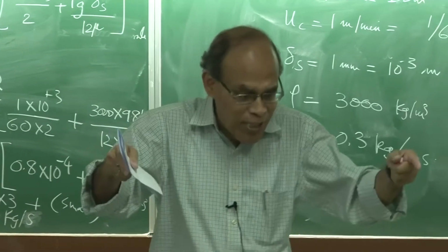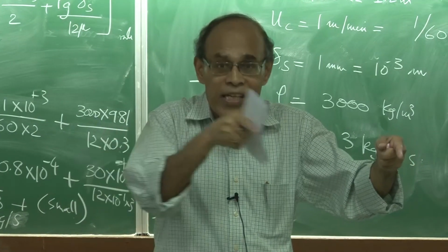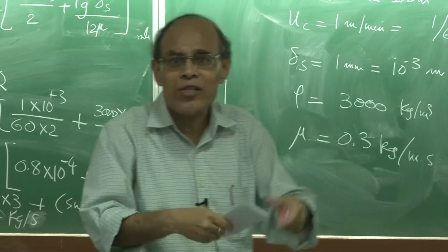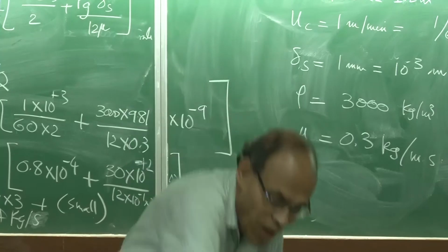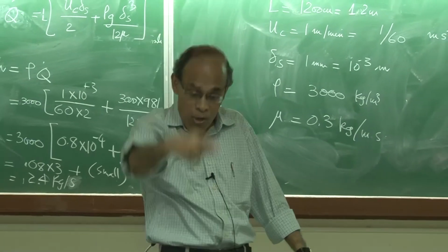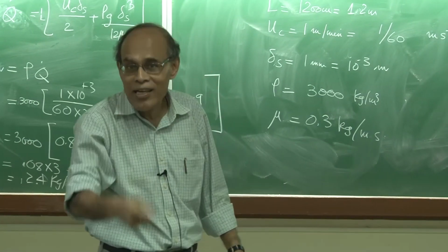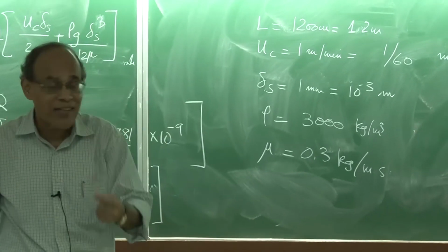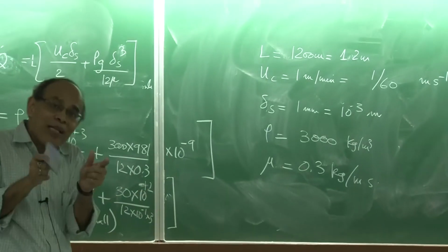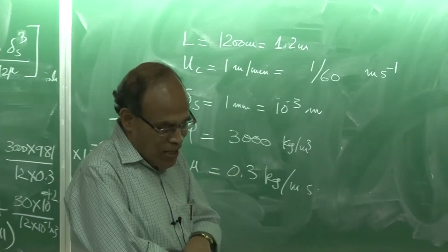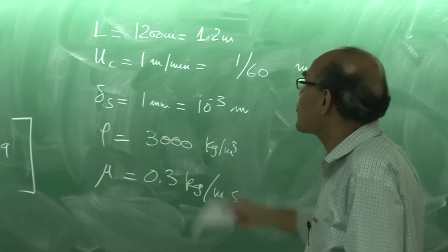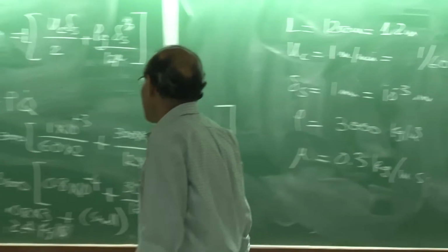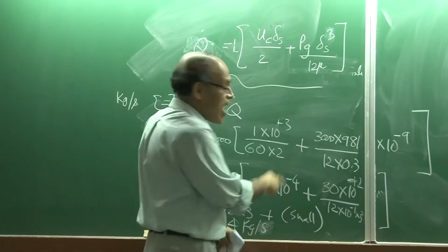So, the powder itself is in a range of states. It is somewhere solid, somewhere crystalline, somewhere liquid. It is a horrendously complex process, and sometimes the mold goes down and then, with the reciprocating motion, it comes up. So within the powder itself, there is a changing flow pattern. Those sorts of complexities I have not dealt with; I have just illustrated in very simple terms that if you do a shell balance within a section of the film, we can have a simple expression, and based on this a first-hand estimate.